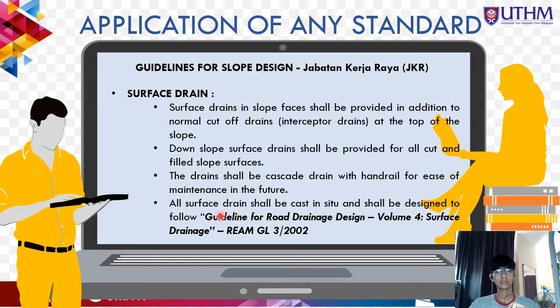All surface drains should be cast in situ and should be designed to follow the Guideline for Road Drainage Design, Volume 4 Surface Drainage, REAM GL 3/2002.